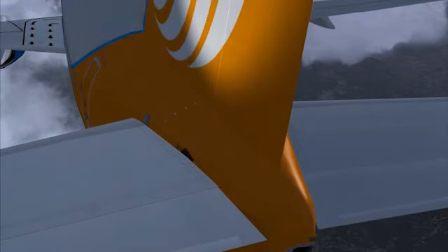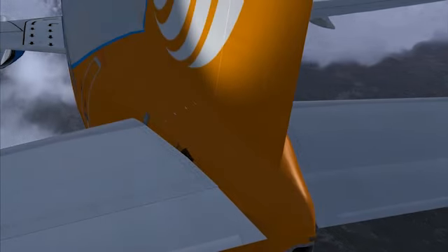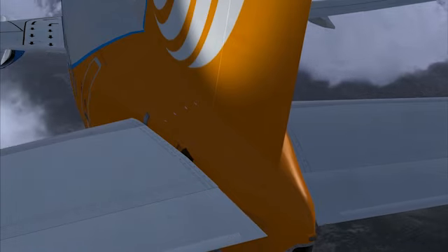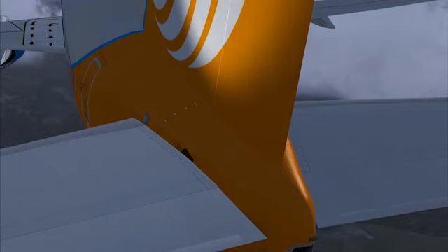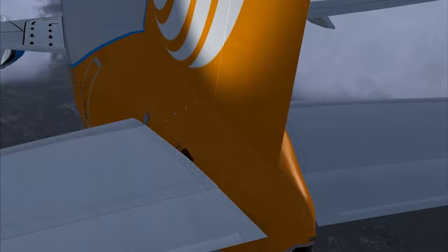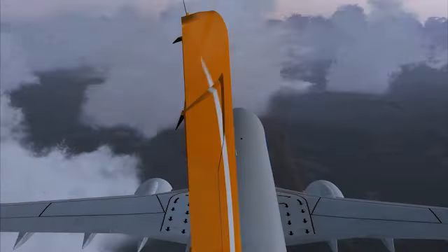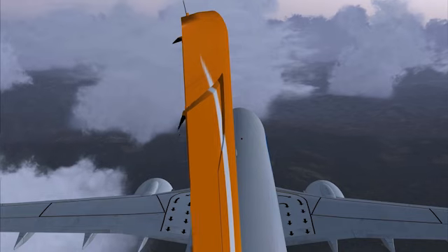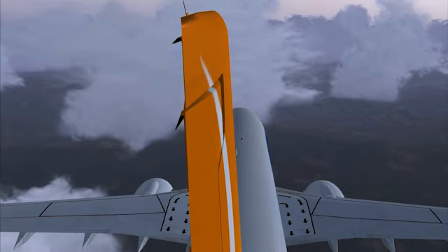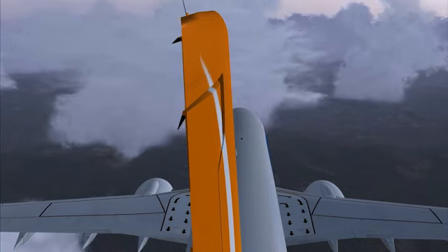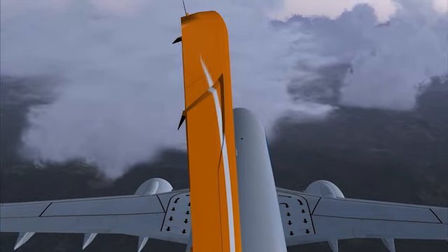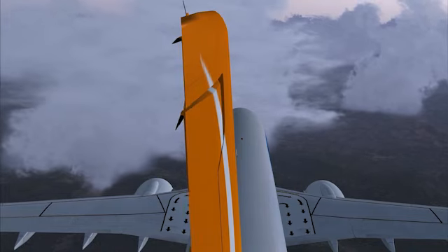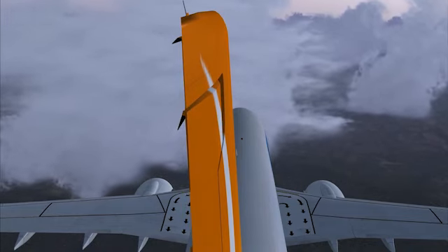As the aircraft moves through the air, it's not only constantly working to overcome the forces acting upon it, but it's also working against environmental conditions like turbulence. Turbulence and Dutch roll are the reasons that yaw damper becomes such an essential system for jet passenger aircraft. This started with the first large jet aircraft being used to fly passengers back in the golden years of passenger service. Yaw damper essentially keeps the aircraft continually coordinated above the vertical axis, eliminating unneeded yaw.